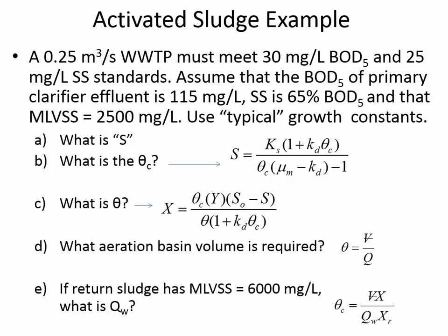The suspended BOD is 0.65 of the 25 milligrams per liter. And so that is 16.25 milligrams per liter.